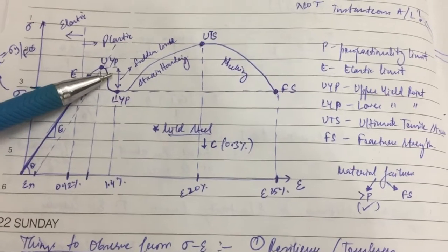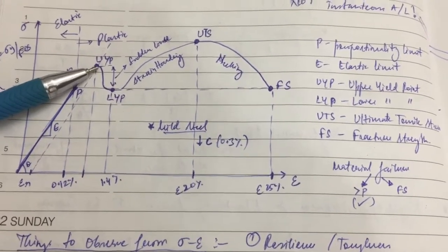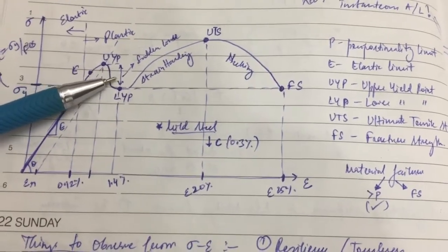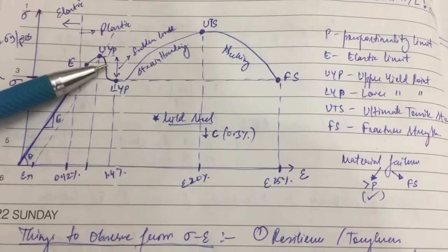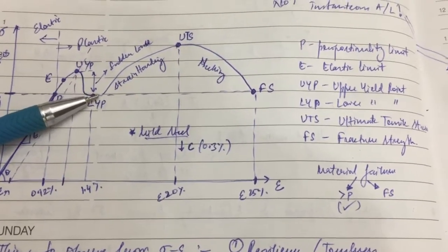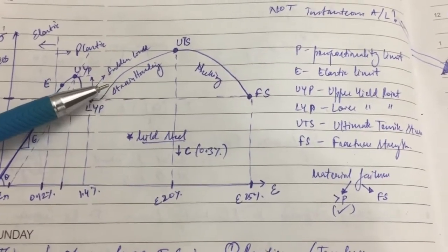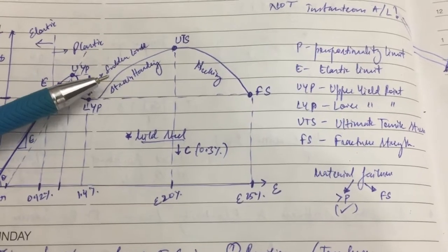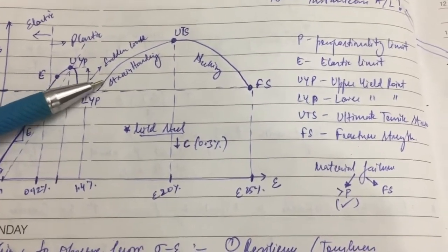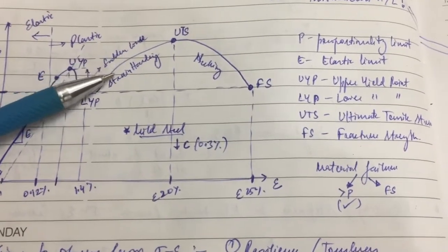Okay, so there is a sudden jump here. This is because of the intermolecular forces. After a certain yield point, suddenly the material loses its strength, so the intermolecular forces lose their bonds. This sudden loss of bonds creates such a sudden variation. After that, stiffening happens. It means the molecules get twisted, and at that time the intermolecular forces are higher, the resistance force is high, and in that case the stress is also high. So this is called strain hardening.